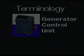The generator control panel plays the major role in controlling the safe operation of the generator. Let's look at the circuitry and inputs that allow it to accomplish this feat. First, terminology. The generator control unit performs many functions besides regulation, but the unit is almost universally referred to as the voltage regulator. Most mechanics simply refer to this device as the voltage regulator or regulator. In actual fact, it performs many functions besides regulation.